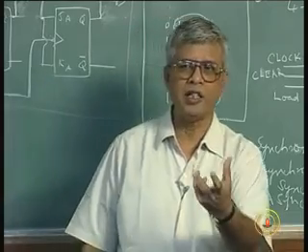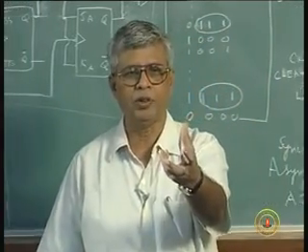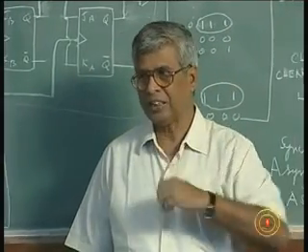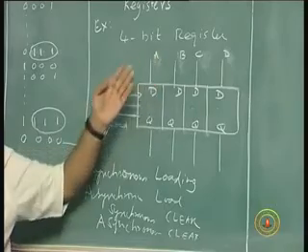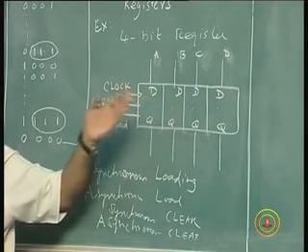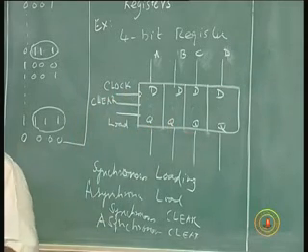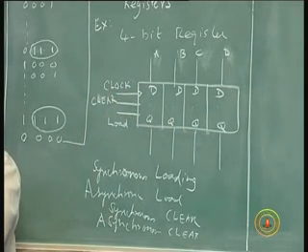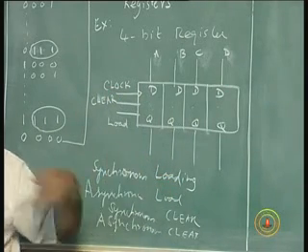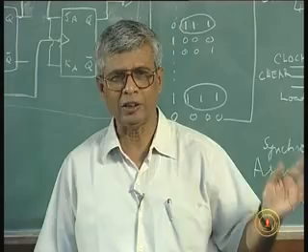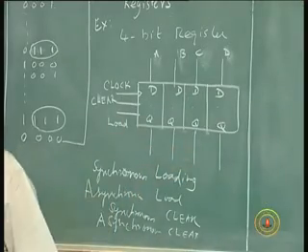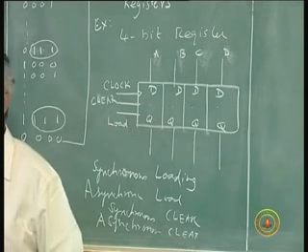So in short, I have these registers, which are bunches or groups of flip-flops. I can put the data in and keep it as long as I want, and take it off, read it off, and use it. If I want to use it again, the same data, I can have data which is stored and read it off again and again. That's also possible, because as long as I do not load new data in, the data is going to remain. Reading off is nothing but using these values. When you read off a value, it does not mean that the data is destroyed. It's non-destructive.